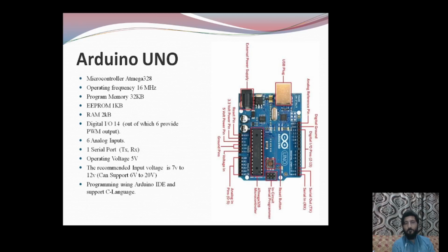Once again, you need the IDE for programming, and it supports C language. It has an external power jack. You can use an adapter, and you can also use a battery on the VIN voltage input port. You can also power it by USB cable. So whatever your need is, you can choose it.